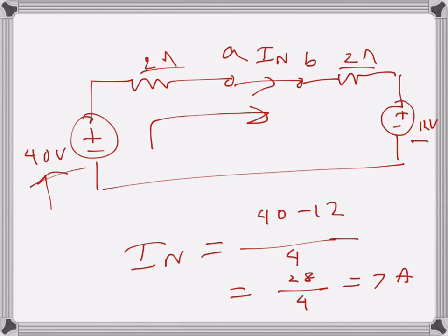Now we need to find the Norton's resistance, which is the resistance seen from here. So I will work with this circuit, because this circuit is essentially the same, and we have seen in previous examples that we will get the same result. So I will just work from this circuit, and I will erase this part now. This is the resistance that I want to see, the value of the resistance, which will be R equivalent, R Norton, let's say, and the sources will be inactive.